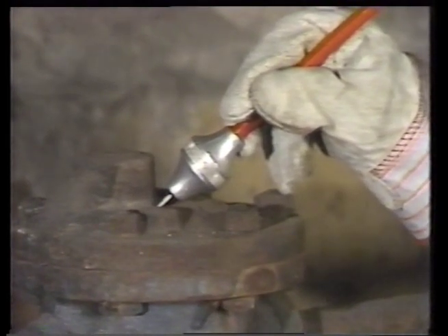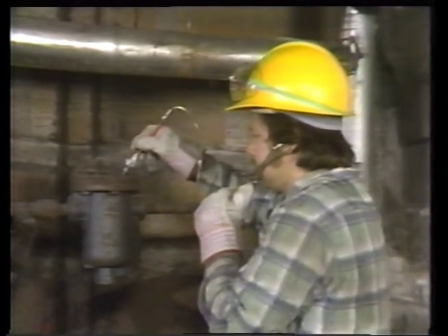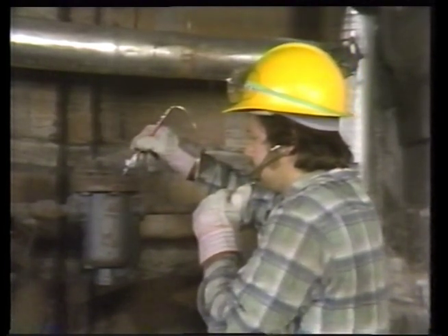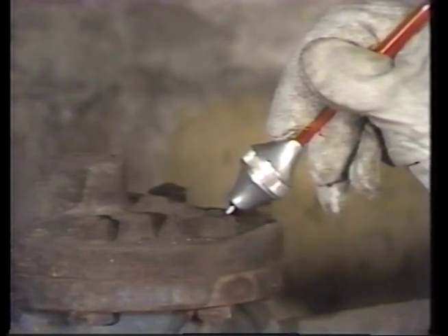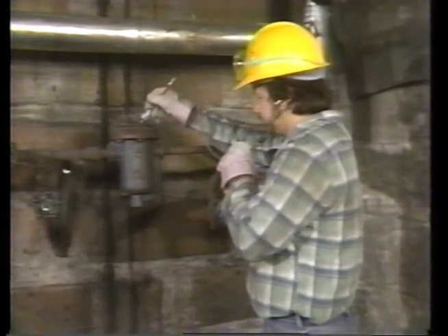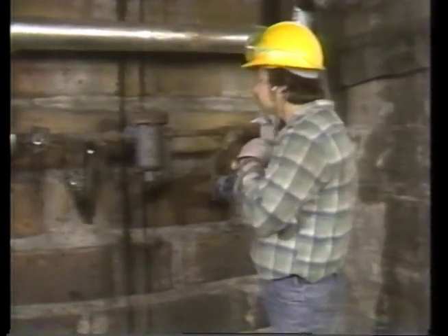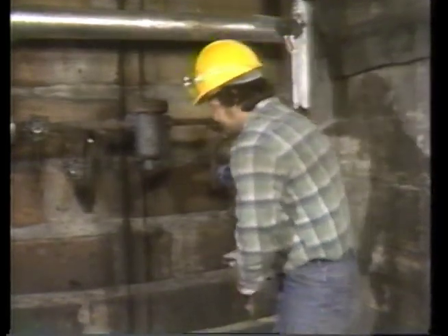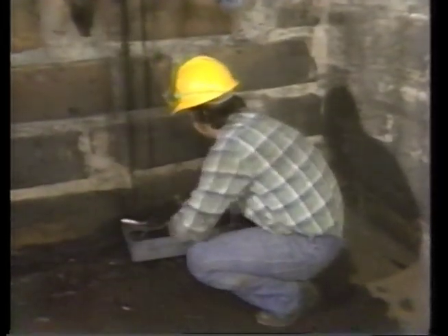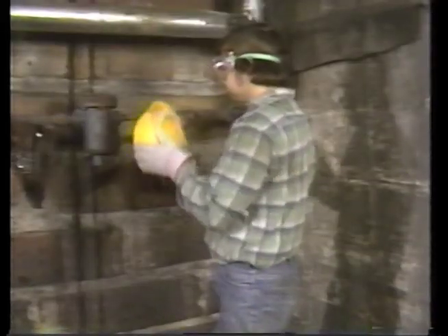It may take a little practice, but you'll soon learn to recognize the sounds made by the trap internals. If you cannot hear any flow through a mechanical trap, it may have failed shut. It's hard to tell for sure because some mechanical traps will, under light load conditions, pass only very small amounts of condensate. Now, this can be very difficult to hear. If possible, visually check the flow to determine whether there is no flow or just low flow. Don't forget to protect your eyes.